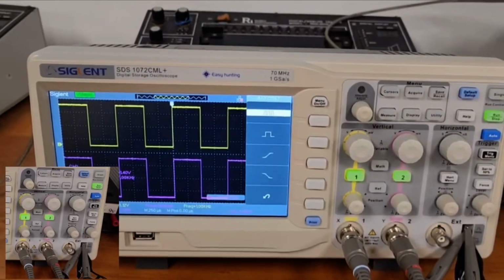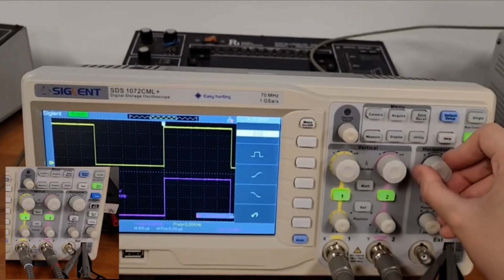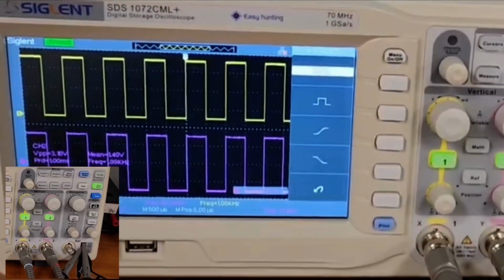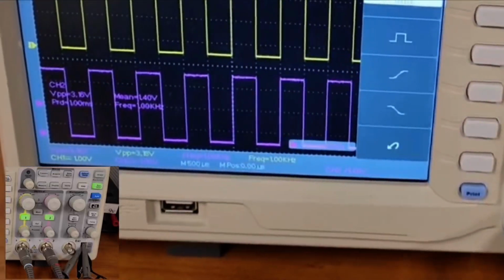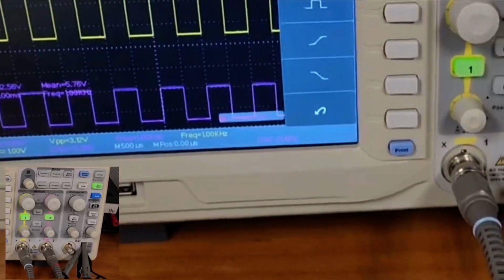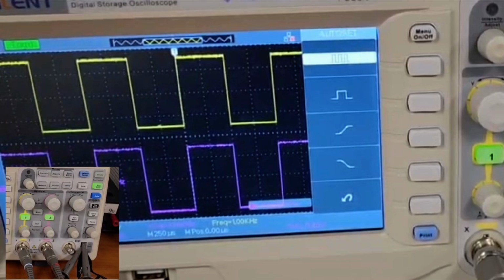Before we start using the oscilloscope, we need to troubleshoot the probes to avoid using faulty probes. So I connected it to the 1k Hz signal provider and grounded it to avoid any noisy signals. And I pressed auto to see if the waveform is accurate. It should be a perfect square 1000 Hz waveform like this if there's no issue with the probe.